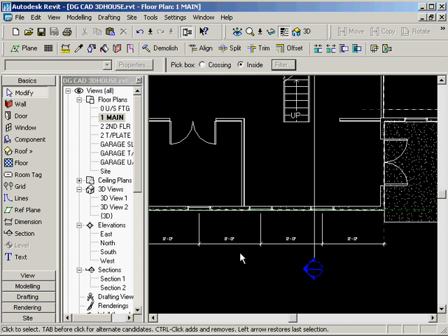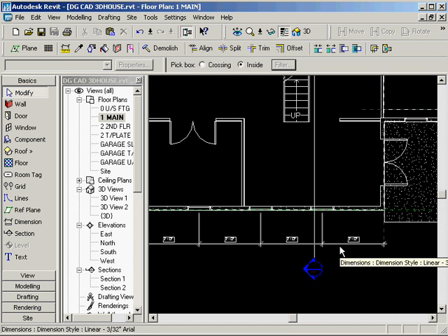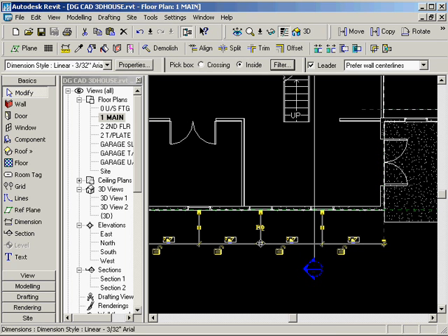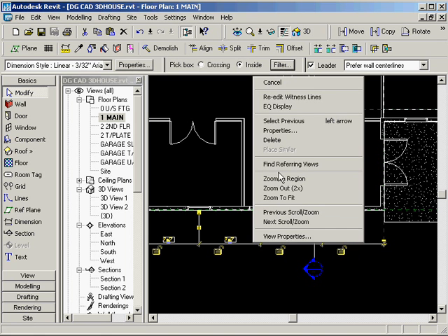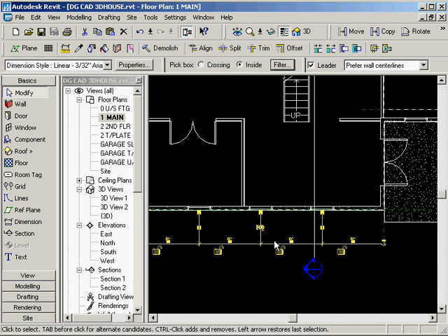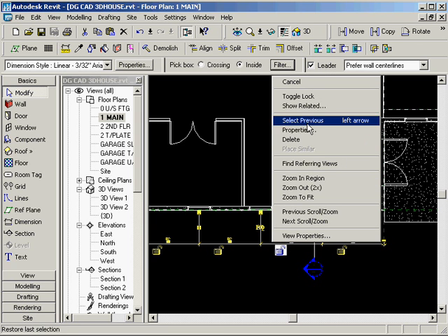So with the dimensions, what I did was I did the equal on the fly, which I believe you have to do. And then after that, I clicked on my dimension. I did a right click, and I didn't do view properties. I did properties straight in here. And here we go here, equal display. Okay, if you wanted to say equal, right click. It's as easy as that.